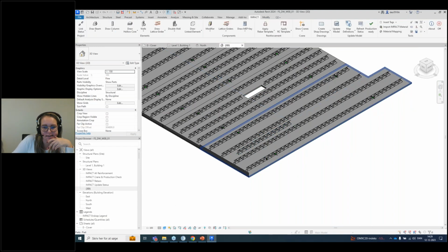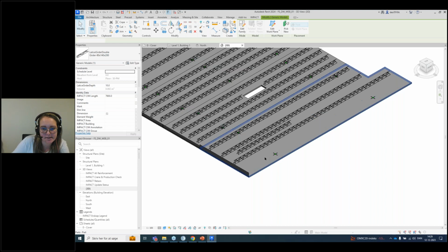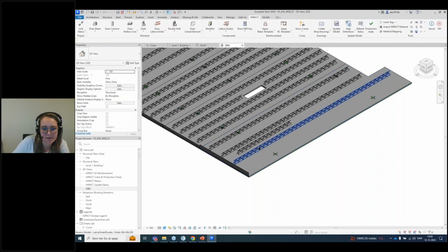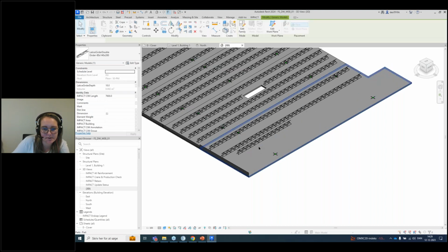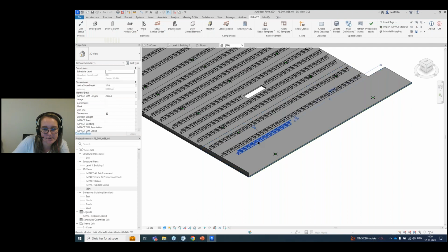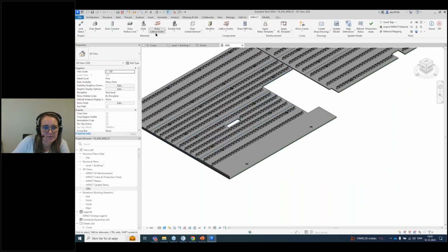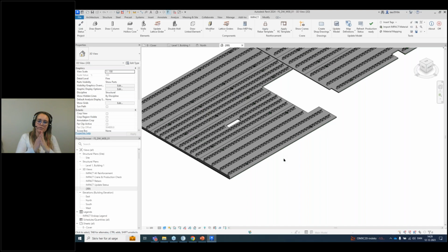If you accidentally delete some lattice girders, let's say we just remove them from here, like this, like that, then there is an option called Update Lattice Girder, which is going to refer to the definition. In the definition, we have set 4 per element with the respective restrictions to the edges and to the holes, and this is what the impact is going to refer to.